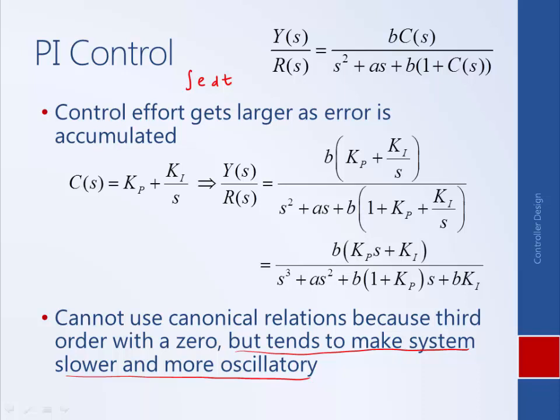And so one reason for that, maybe you can imagine, is in order for the effect of the integrator to take hold, you need to sort of sum up the effect of the error. So if we can sort of imagine our error doing something like this, in order for the effect to build up, we need to add up the area under the curve. But if the error switches sign, then the direction that the controller is pushing doesn't necessarily change sign.